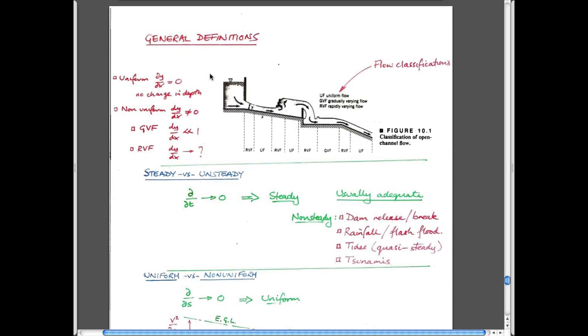The second item is that when we looked at those videos, we saw that in terms of fluid mechanics, those flows on the New River would be what are referred to as rapidly varying flows. You can imagine a variety of different flow regimes where you have water that's almost static, comes out of the bottom of a sluice. We've talked about free jets. For some reason, it miraculously changes from this very fast and shallow flow regime into a slower but much deeper flow regime,